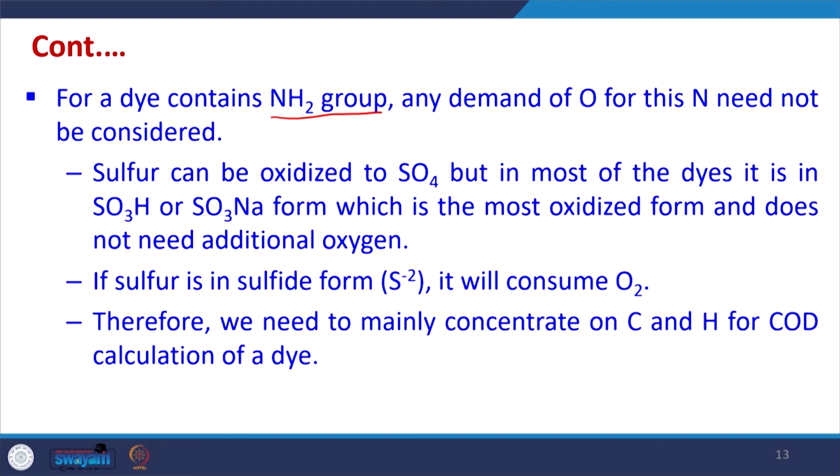And sulfur can be oxidized to SO4, but in most of the dyes it is in SO3H form or SO3Na form, which is the most oxidized form and does not need additional oxygen. So, for sulfur also, if in the dye it is in this form or this form, we need not calculate the oxygen demand for this sulfur.